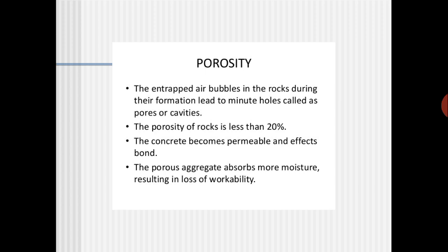If the bulk density is going to increase, of course the strength of the overall concrete is going to reduce. The concrete becomes permeable and affects the bond. This is very important. The bonding between the aggregate, the cement and the sand is very important. If any cracks are observed in your aggregates, normally it is going to affect the performance of the concrete. The porous aggregate absorbs more moisture